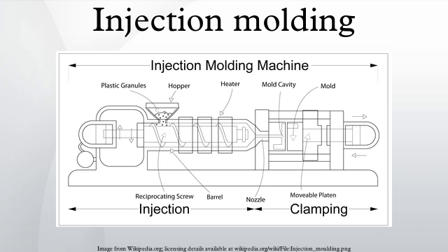Tolerances and surfaces. Molding tolerance is a specified allowance on the deviation in parameters such as dimensions, weights, shapes, or angles, etc. To maximize control in setting tolerances, there is usually a minimum and maximum limit on thickness, based on the process used. Injection molding typically is capable of tolerances equivalent to an IT grade of about 9 to 14. The possible tolerance of a thermoplastic or a thermoset is ±0.200 to ±0.500 millimeters. In specialized applications, tolerances as low as ±5 micrometers on both diameters and linear features are achieved in mass production.